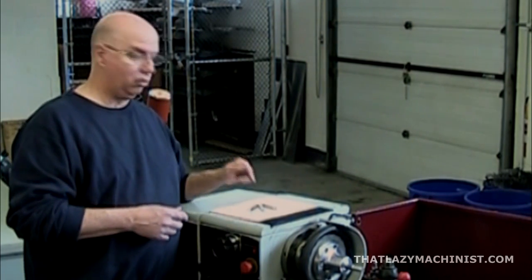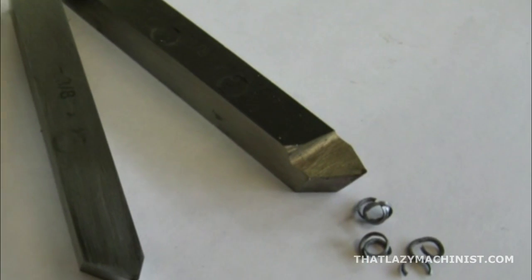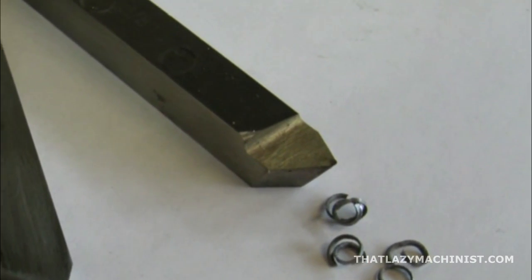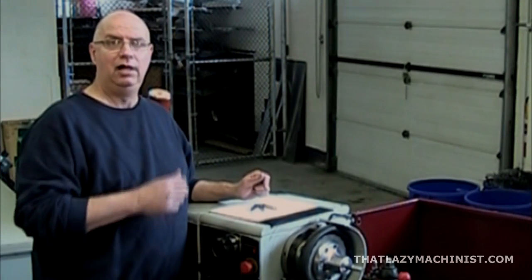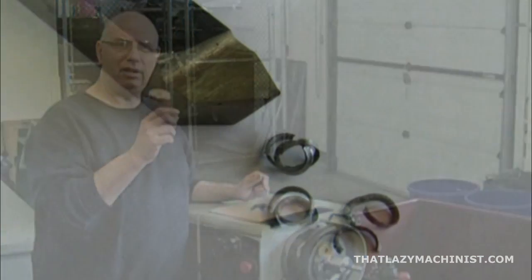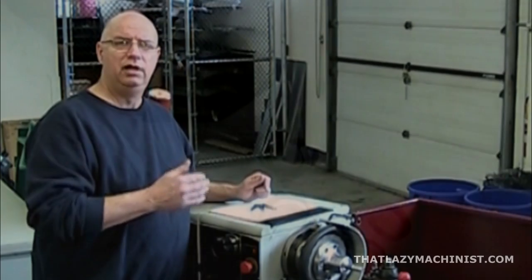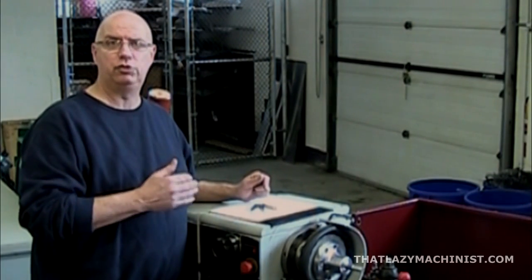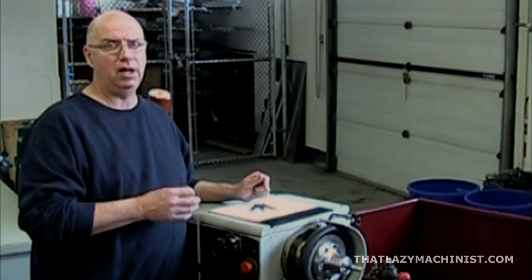And our last tool, the one at the very end here, was our tool with the positive cutting angle. We can see that the chips produced by that positive cutting angle have a very large curl and that they broke off in relatively short segments. They're also a lot duller than the chips produced by the neutral angled tool. This is an indication that we're probably cutting a little bit on the cold side.